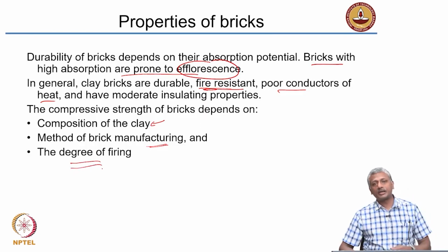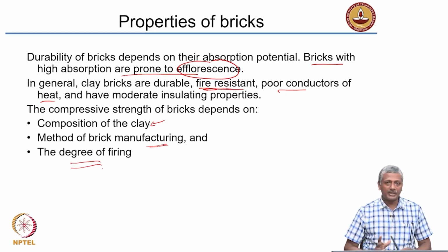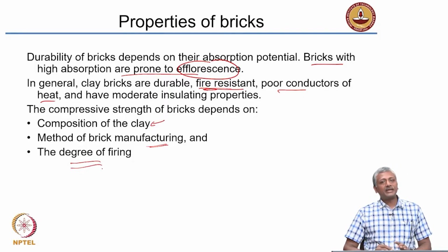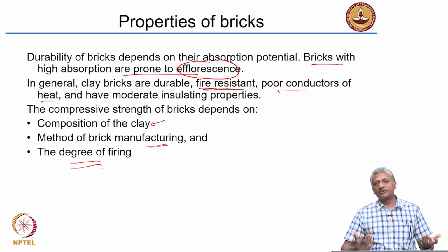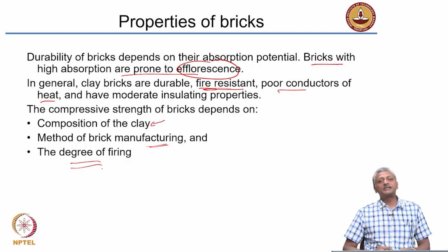At what temperature does your kiln operate? Can you control the temperature? Can you control the time that the burning is actually done? And that is also very important, because not often do you find the kilns in rural areas having any kind of control on the temperature and the duration of the process. Okay. So if you can engineer this, if you can actually design furnaces where you can control the rate of temperature increase, decrease, the time of maintaining the temperature and so on, you can come out with very high quality bricks.